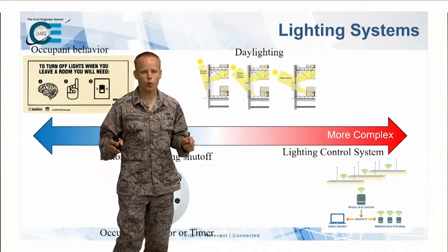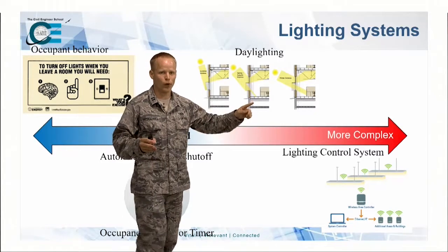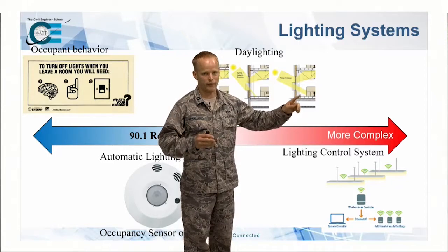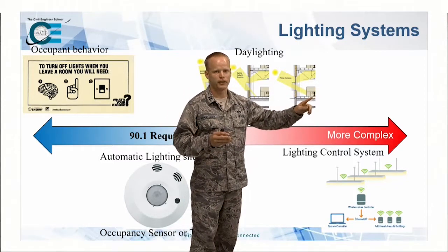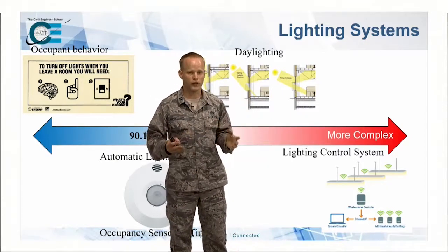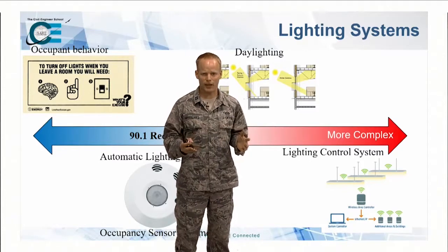Then, possibly in the winter, you want to let that sunlight in, so now that heats up your floor. Then, even later in the winter, you want to let more sunlight in, but you don't want it onto your occupant. So you'd have to block the light in some way, possibly with a desk or how you arrange it. So it gets complicated.